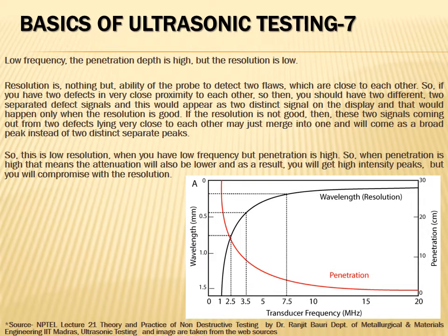When the signal comes back after the back wall, maybe the signal of one defect has a high energy or high intensity peak, and the second one has a low intensity peak. These two signals may merge and come on the display screen as a single one. That is the big issue.